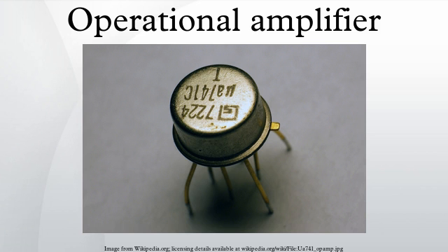Input offset voltage: the offset null pins may be used to place external resistors in parallel with the emitter resistors of Q5 and Q6, to adjust the balance of the Q5/Q6 current mirror. The potentiometer is adjusted such that the output is null when the inputs are shorted together. Nonlinear characteristics: input breakdown voltage: the transistors Q3, Q4 help to increase the reverse VBE rating.